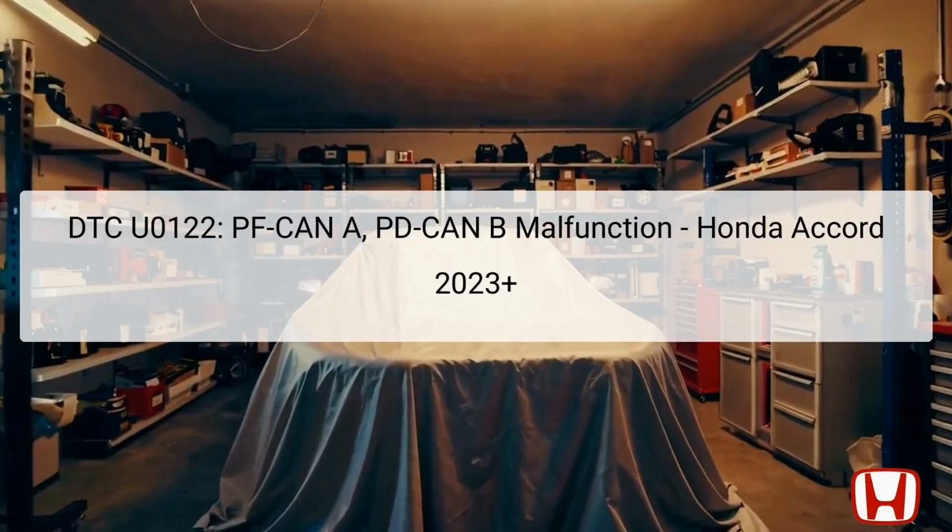DTC code U0122 indicates a malfunction related to the PF-CAN-A and PD-CAN-B communication lines. This malfunction involves the Powertrain Control Module (PCM) and the Vehicle Stability Assist (VSA) modulator-control unit, both critical components in the vehicle's operation. The PCM is responsible for managing engine performance and vehicle dynamics, while the VSA modulator-control unit helps maintain vehicle stability by controlling braking and engine power.